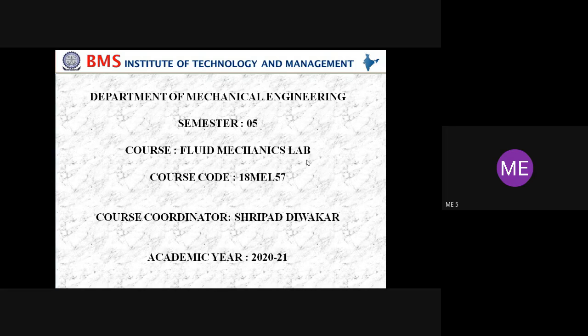Third one is based upon the direction of flow with respect to the runner. First one is tangential flow turbine, where the water enters in a tangential direction to the runner blades. Example is Pelton wheel. Second one is radial flow turbine, where the water enters and leaves radially from the turbine. Example is Francis turbine. Third one is axial flow turbine, where the water enters and leaves axially from the turbine. Example is Kaplan turbine.